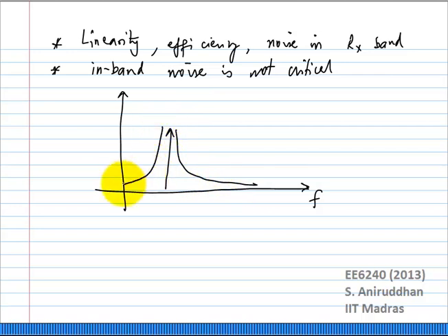And if you look at the phase noise curves of the signal you are trying to produce, it looks something like this. And if this is, let's say, 30 dBm, and let us say the phase noise is, let us take, let's say minus 130 dBc per hertz at the RX offset.